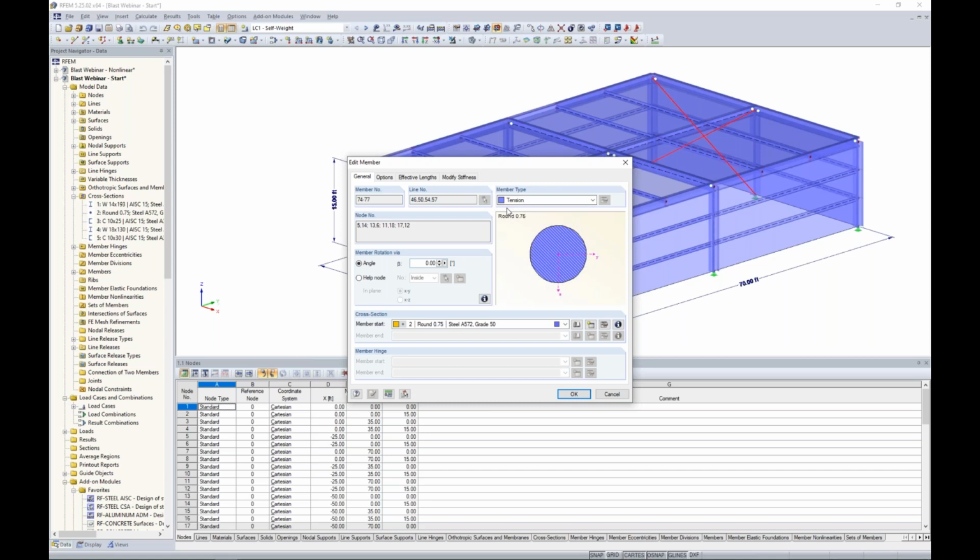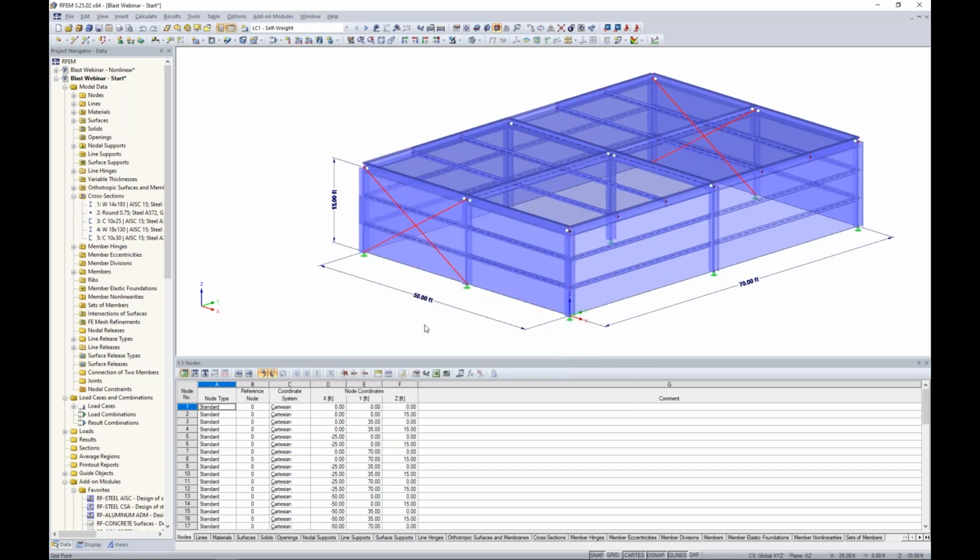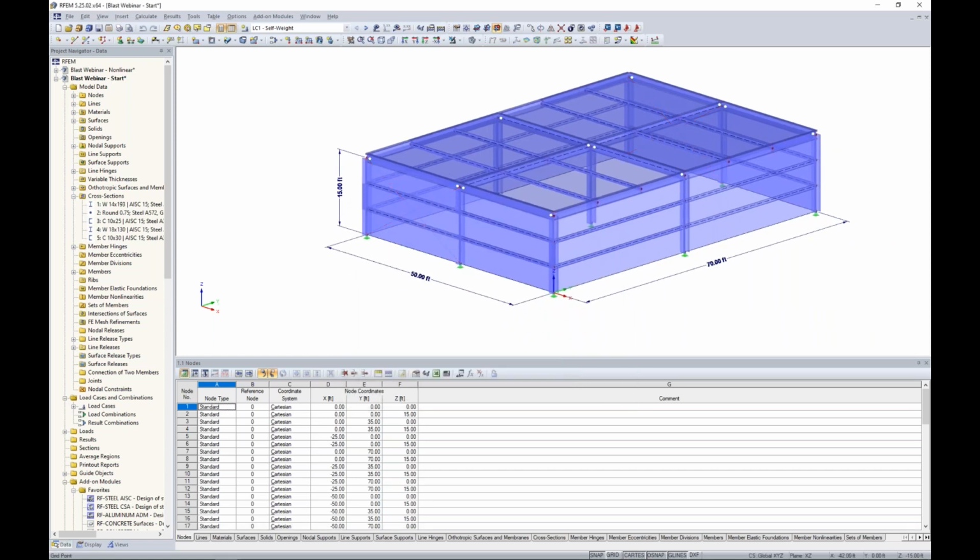So in the program, these will take only tension forces. It's some type of cable element, we'll assume. So when the program experiences compression within these elements, it will completely take it out of the analysis, but RFEM being a nonlinear analysis, it can reactivate these if we see tension again in a subsequent iteration. So let's just keep that in mind for those X braces.